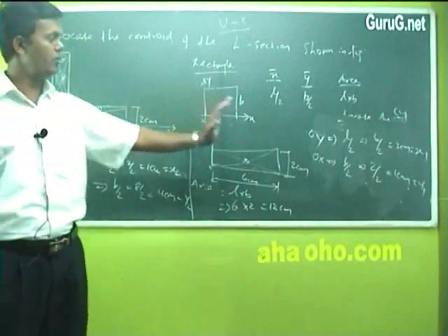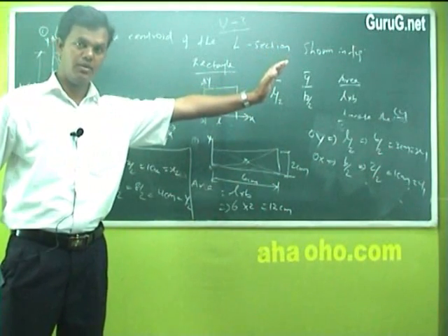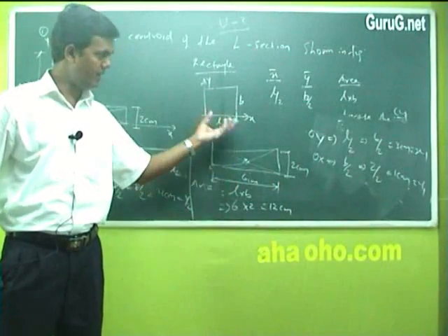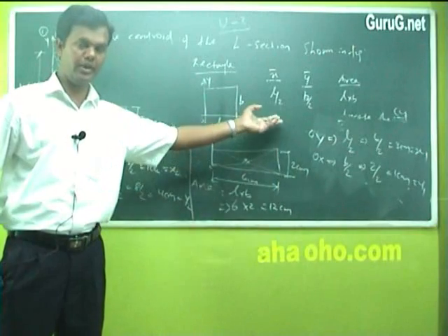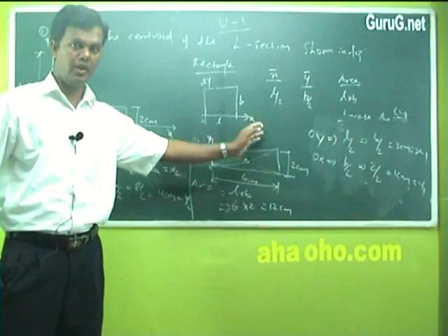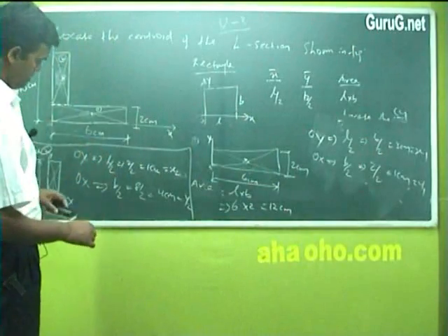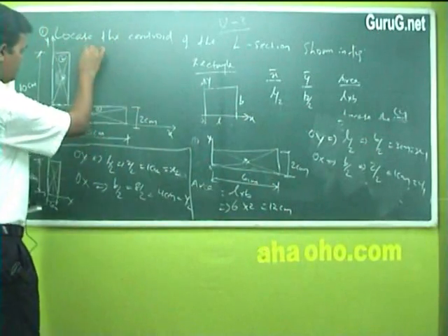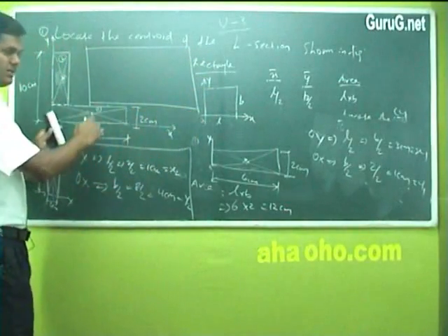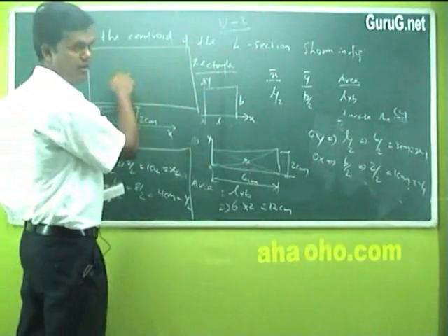So this is the basic step for any sketch when you find out the center of gravity. This one we are going to substitute in the formula: a1 x1 plus a2 x2 divided by a1 plus a2. Again you go for the y bar value: a1 y1 plus a2 y2 divided by a1 plus a2. Now I'll write the formula here. Let me write it here because it's still congested. I'm just keeping this figure without erasing to make you understand, because the final answer will be here now.